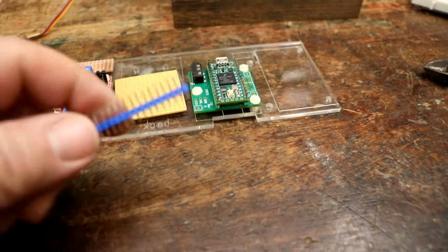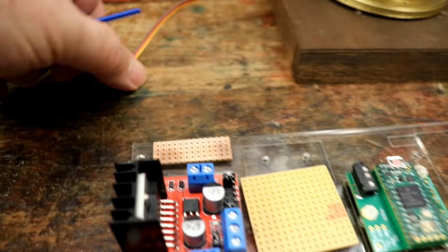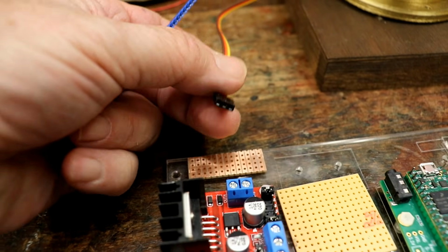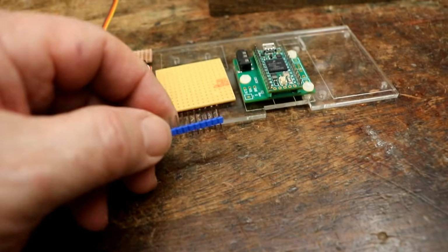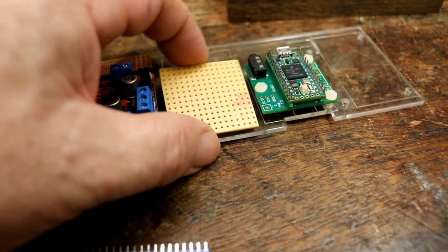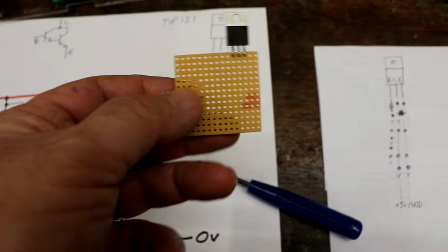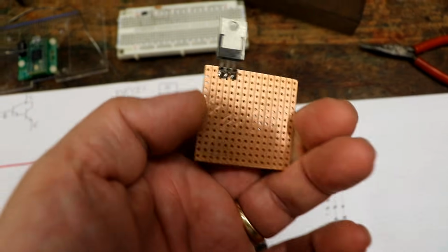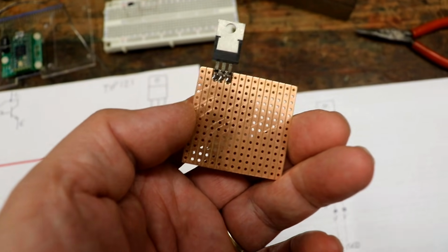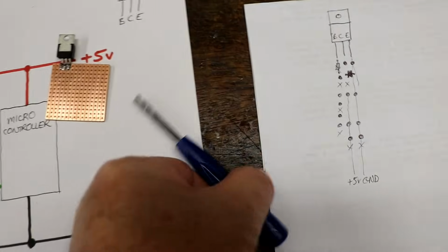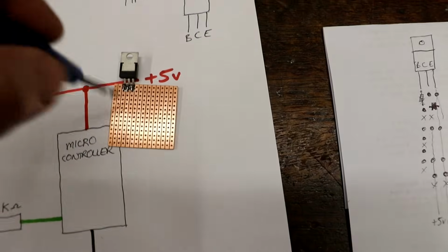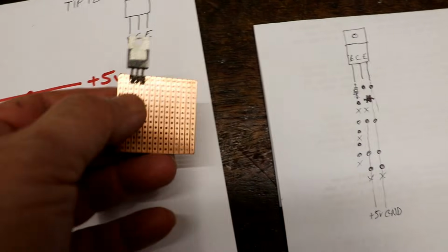And the other thing I'm going to do, just remembered, here we are, look, the end of the servo motors always end up terminating in one of these three-way connectors, plugs or sockets or whatever. So I'm going to use some of these header pins and use part of this prototype board just to be able to connect them handily. Because the great thing about this prototype board is that you've just got lots of thin copper strips, each insulated from the next. And if you want to break one, you just use a tool like this, which is basically a drill bit in a handle. And you can just twist it a couple of times round and it'll break one of the tracks.